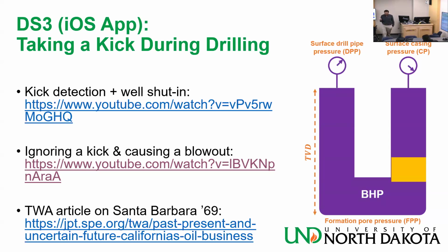Now, you may also have encountered a situation where they were drilling with oil-based mud and it was a slow kick. So the kick was entering the mud. It was dissolving in the mud. And they were drilling with the wrong mud weight, but they didn't know it because the kick was dissolving in the mud. And you don't get any indication of the kick like that, okay? Until you have so much gas that the mud cannot dissolve any other gas coming in from the rock, and then you get a kick, again, you look at it as a separate phase, you know? That was oil-based mud. It was some sort of oil-based mud. It wasn't diesel.